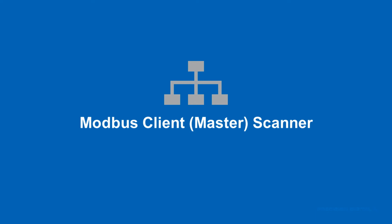So let's first talk about Modbus Client Master Scanner Mode. So this is one of those 3 capabilities you get. You get that client mode for Modbus. Just to be clear, the standard Consolidator Plus is a Modbus server or slave device, meaning it will respond to Modbus requests from a master. So if, for example, you had a PLC in the control room and you wanted to pull out some data from a Consolidator Plus, you can do that on the standard Consolidator.